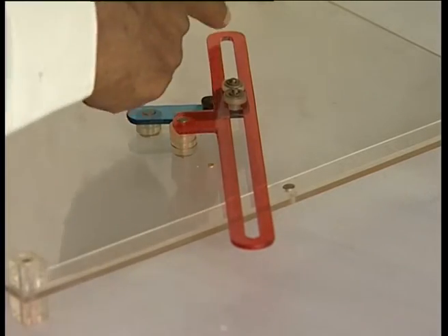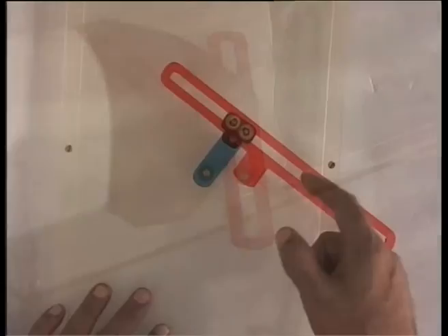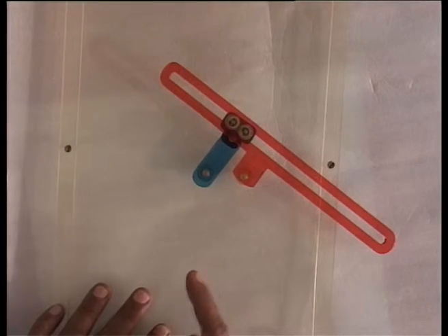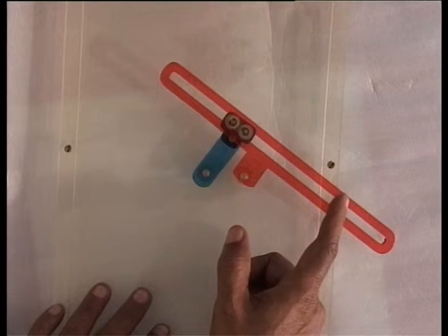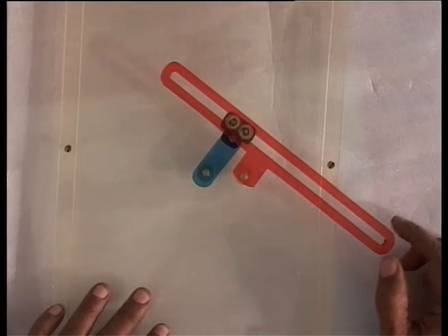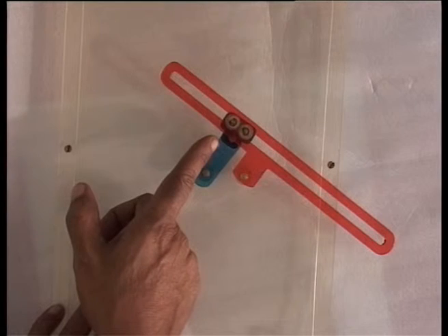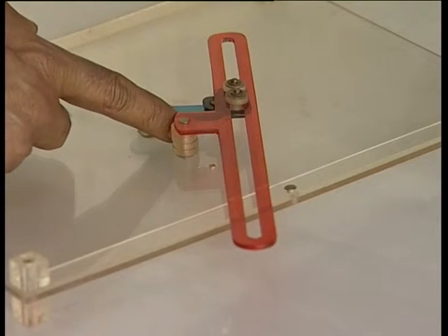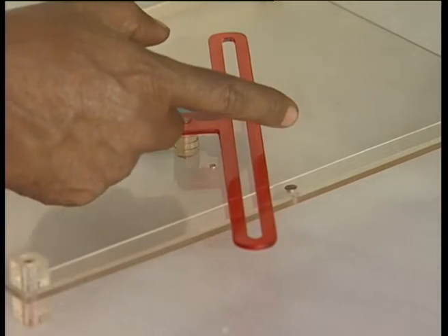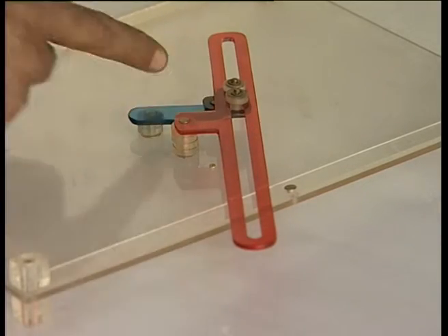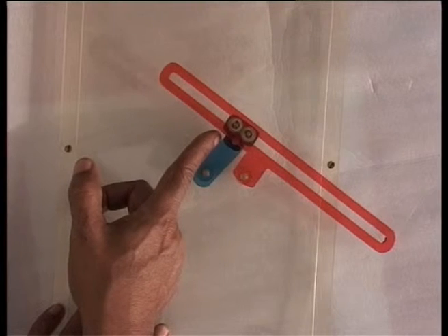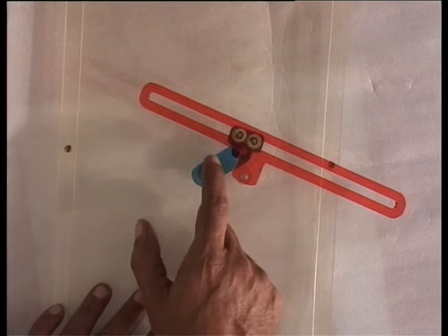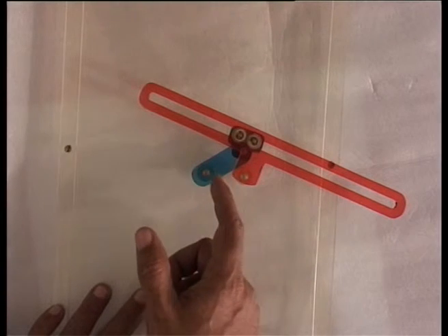This is that common tangent that I was trying to draw between those two circles. This line is parallel to that common tangent, and consequently this has reached its extreme position, it cannot be further inclined. However, this link can still go, and as you see from this extreme position it is returning, that is, it is rotating counterclockwise, though this link is still going clockwise. And this is the extreme position of this link, and now it cannot go any further, it has to return.